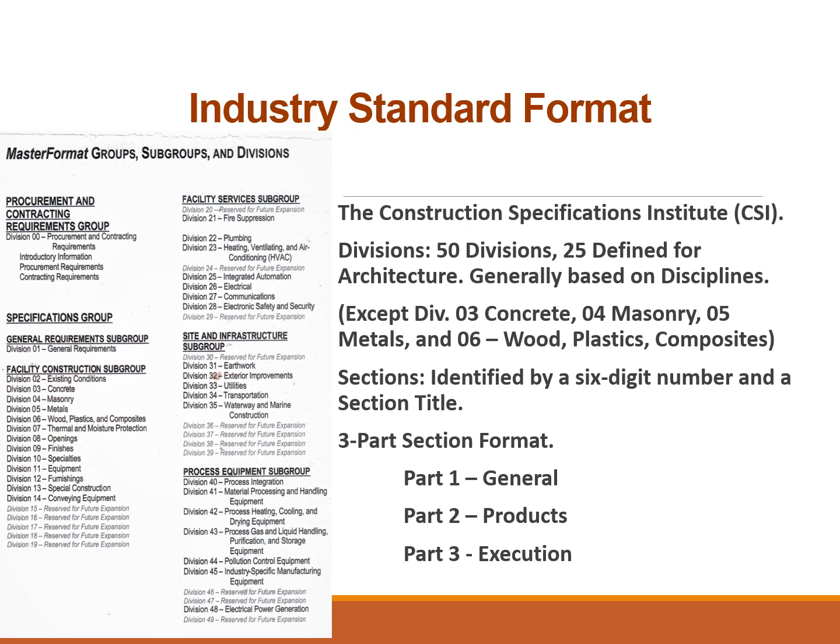As you can see in the MasterFormat groups on the left, we now have the procurement groups, which are division 00, which I like to call division uh-oh, because they're primarily legal, and technically architects shouldn't be writing that. The best they should do is give standards documents to the owner and instruct the owner to have their lawyers look at it.